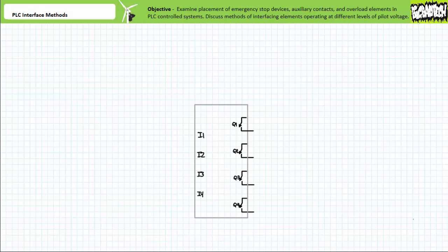You will recall that the fundamental operational principle of ladder logic is the establishment of two different levels of power: pilot and primary. Pilot or control signals are ordinarily low current, low voltage, low power signals that solely coordinate the action of interface elements like contactors and solenoid operated valves. Primary signals, in contrast, are high current, high voltage electrical or high flow, high pressure hydraulic or pneumatic input that does the actual work. When an interface element like a contactor or a solenoid operated valve is commanded to do so by a pilot signal, these interface components make or break connection to primary input.